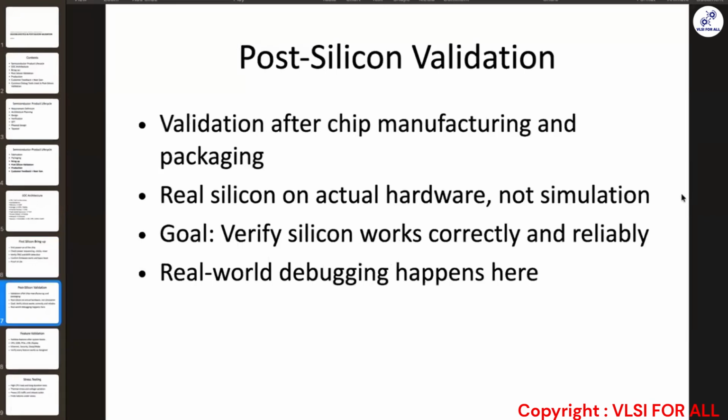Then the next one is post silicon validation. So in this phase, once the silicon is booting fine, you check all the features of that particular platform. When you say post silicon validation, you're not only qualifying that particular silicon, but you may have to check the entire ecosystem, whether it is working or not.